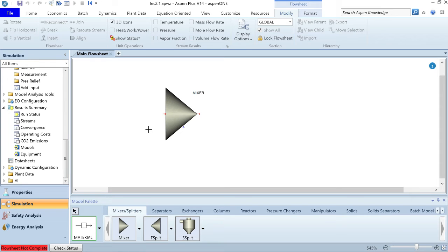As you enter the main flowsheet window, you can notice arrows with different colors are active now, and arrows indicate the connection ports. The red arrows indicate the required connection streams and the blue arrows indicate the optional streams. You can hover the cursor over the port to see the details of the connection port. For instance, this indicates the required feed stream. Here you can insert one or more inlet streams.